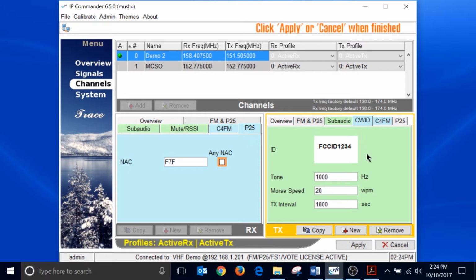CWID will also only show up if it's in the signal screen. This is the field where you put in your FCC call sign. You can use whatever frequency you want. I like 1000 Hertz. Morse code speed of 20 words per minute, and 18,000 seconds, which is 30 minutes between IDs.